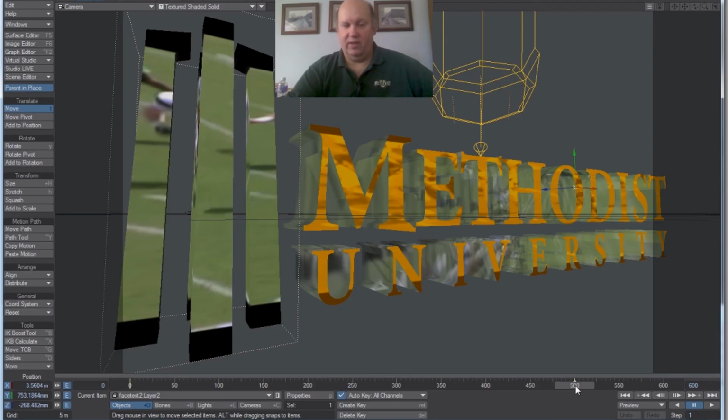Now another thing, you can have keyframes for different things. Right now this is set up for objects. I'm also going to set it up for the camera because that's actually more important to me now. So if I click on the camera, I'm going to create keyframe again, and there it is. So the camera position at 500 is currently set. And we want to change that because we want the 500 frame to look exactly the way we want it to look. So one of the first things we want to do with that is to provide a background that we can sort of mold this to.